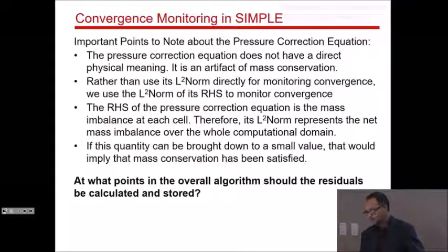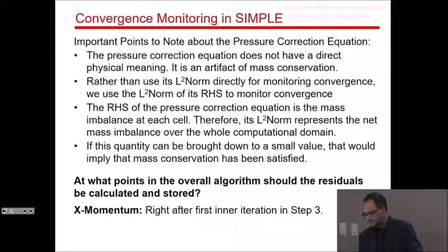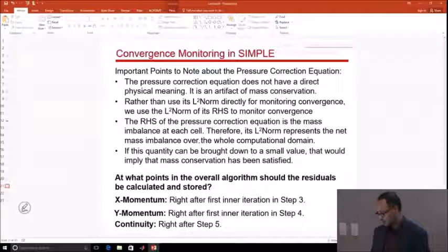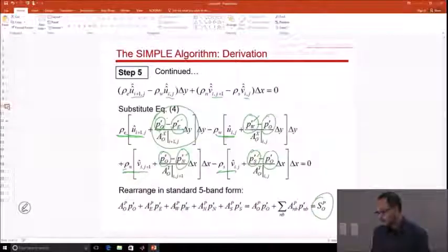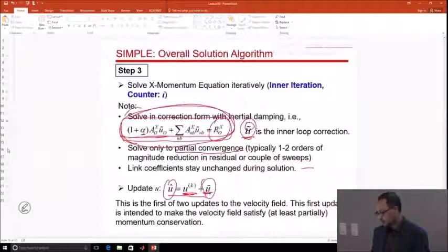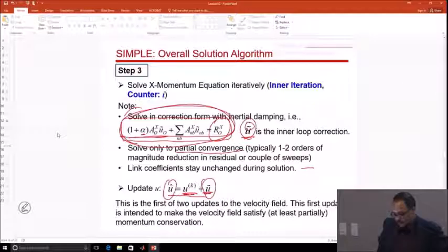So at what points in the overall algorithm should the residuals be calculated and stored and of course monitored? So X momentum, we are saying right after the first iteration in step 3. Now, instead of scrolling, let me break out of this and it's easier to do. Go back here, yeah, there is step 3. So step 3 is solving your X momentum equation. Okay, so what we're saying here is